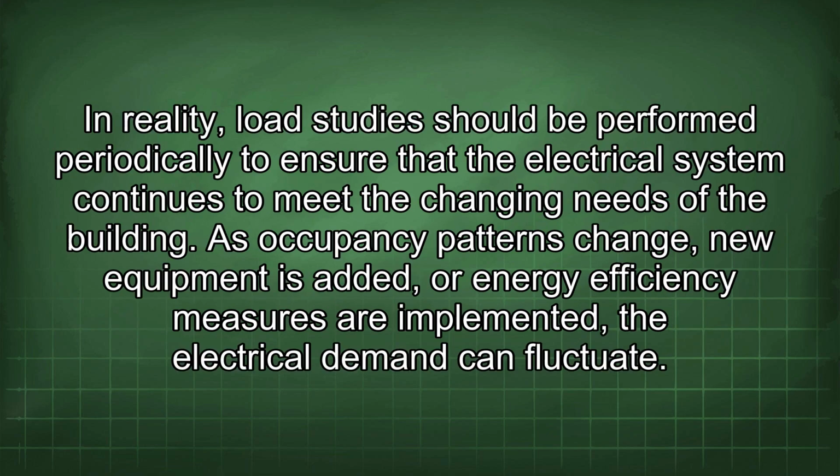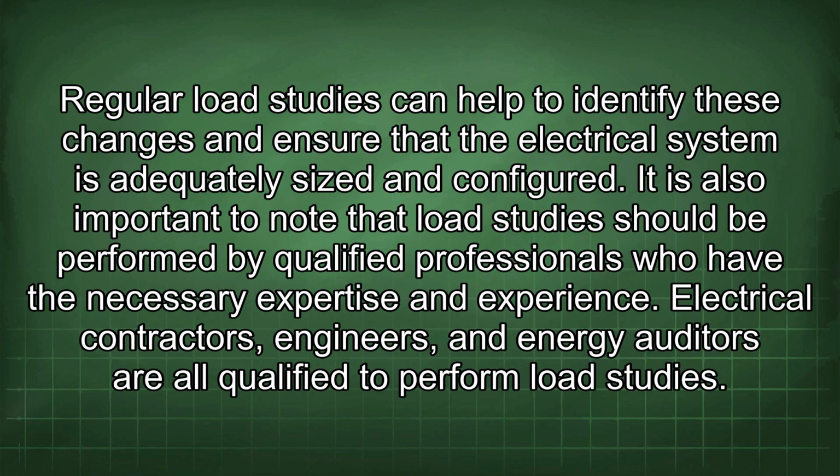In reality, load studies should be performed periodically to ensure that the electrical system continues to meet the changing needs of the building. As occupancy patterns change, new equipment is added, or energy efficiency measures are implemented, the electrical demand can fluctuate. Regular load studies can help to identify these changes and ensure that the electrical system is adequately sized and configured.